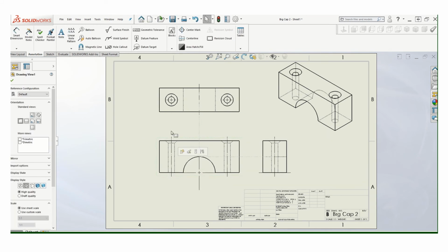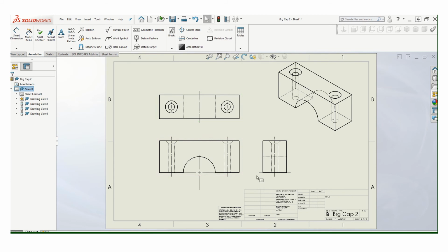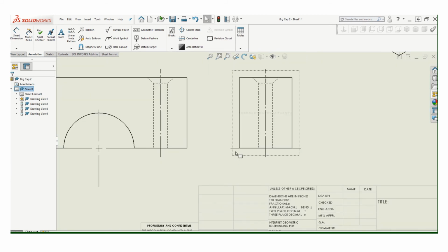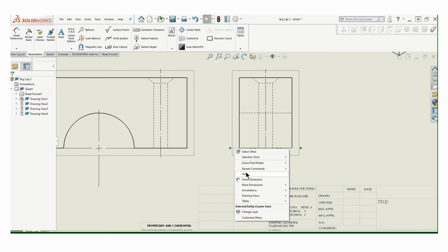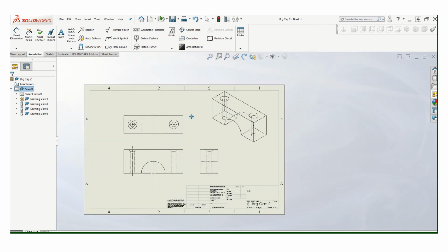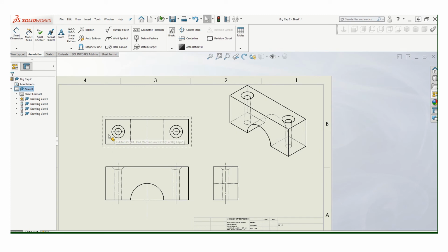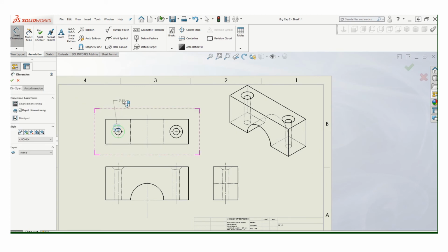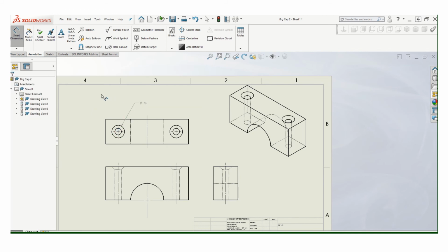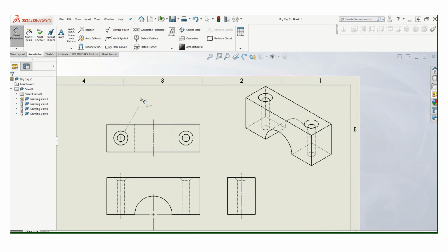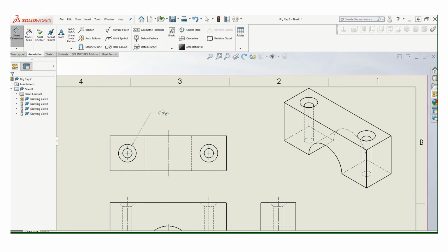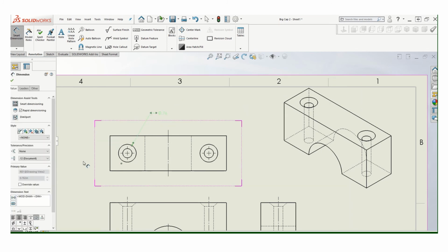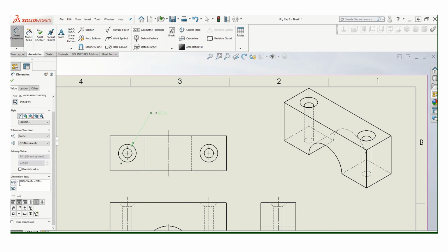The big thing I really wanted to show you, let's see, I can hide that. Got carried away there. We should hide that one. It's how to do the call out for a countersink. We can try dimensioning it normally, and you're just going to get the hole, and that's fine, because then I'll just customize that to however I want it to look. Let's double click on that. First of all, there's two of those, so I'm going to do a 2x space, diameter 0.76.